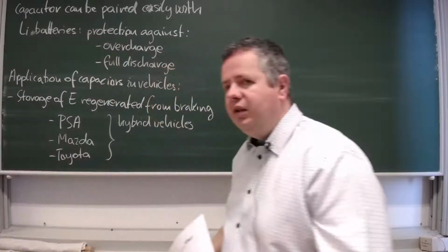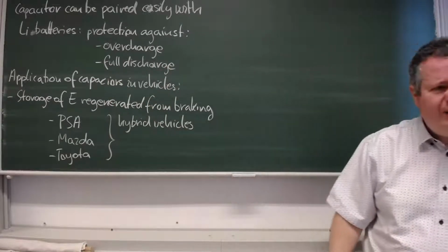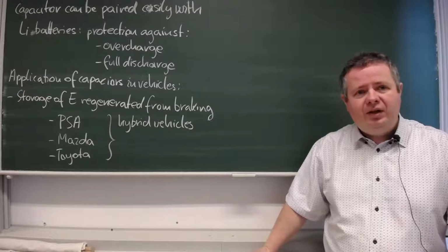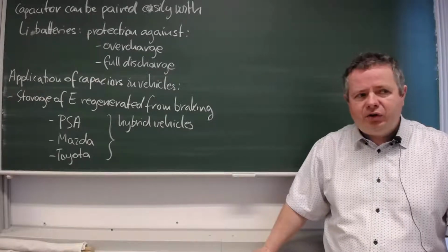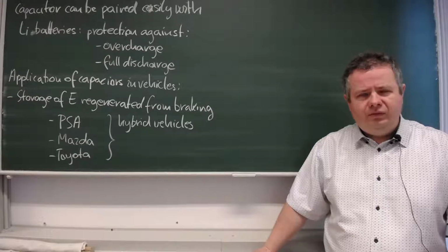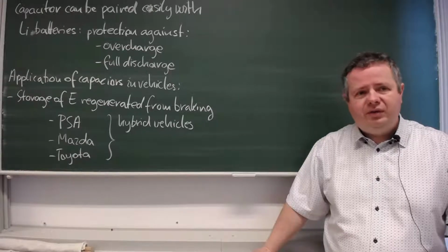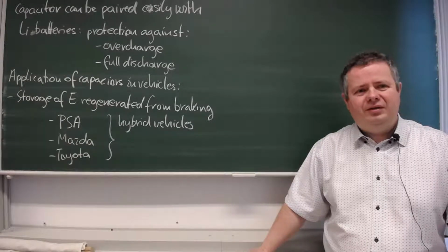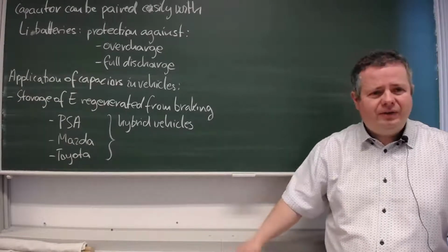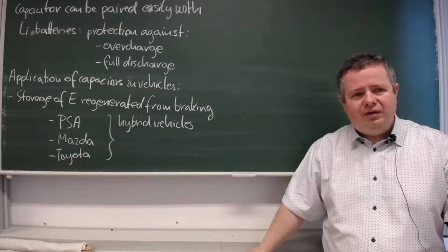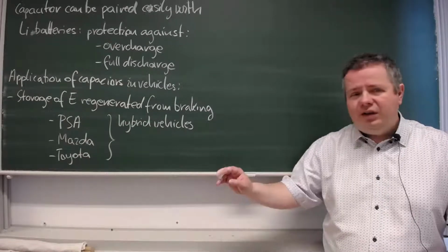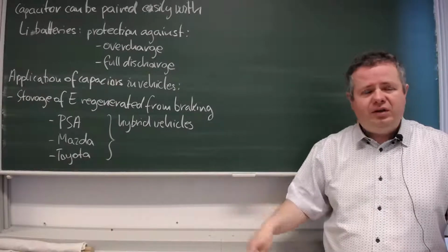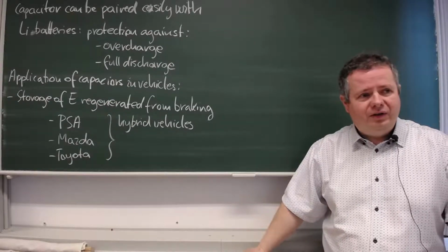I mean hybrid, these are the so-called mild hybrids. So they get a low tension hybrid subsystem, and the car is driven mostly by the internal combustion engine. Typically, this is like the new Suzuki Swift, where the engine does not stop. It's always working, stops just at red traffic lights, but it's always driving the car. But for braking and accelerating, you get a large capacitor that helps. It stores energy at braking and puts back when accelerating. Okay?